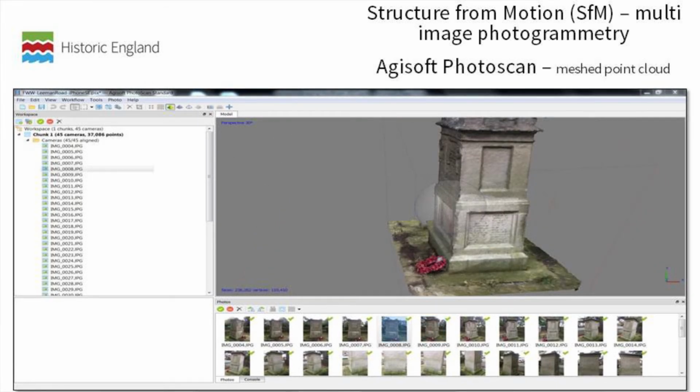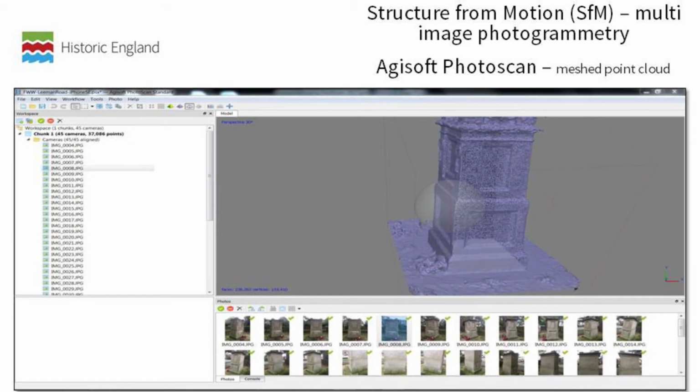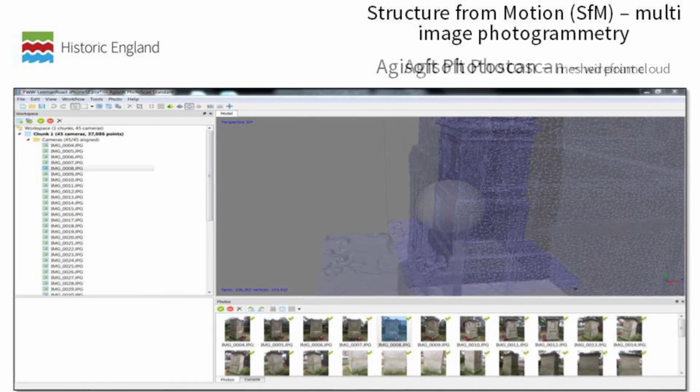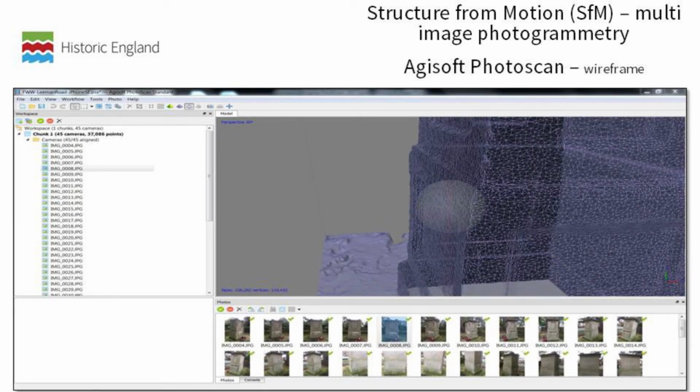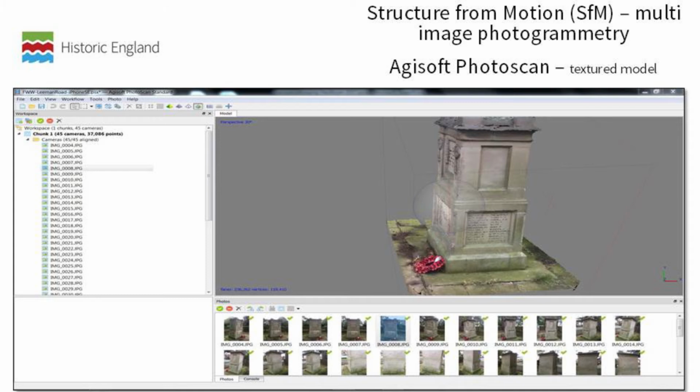The point cloud is normally converted into a mesh, which is all the points connected by lines, and those lines form triangles, and those triangles have surfaces. So that's, hopefully you can see that there. Point of having the surfaces is that you can then apply a photographic texture to the surface and get a much more photorealistic model than basically the dense point cloud, which is each point is given a color, but the gaps in between obviously don't have a color.